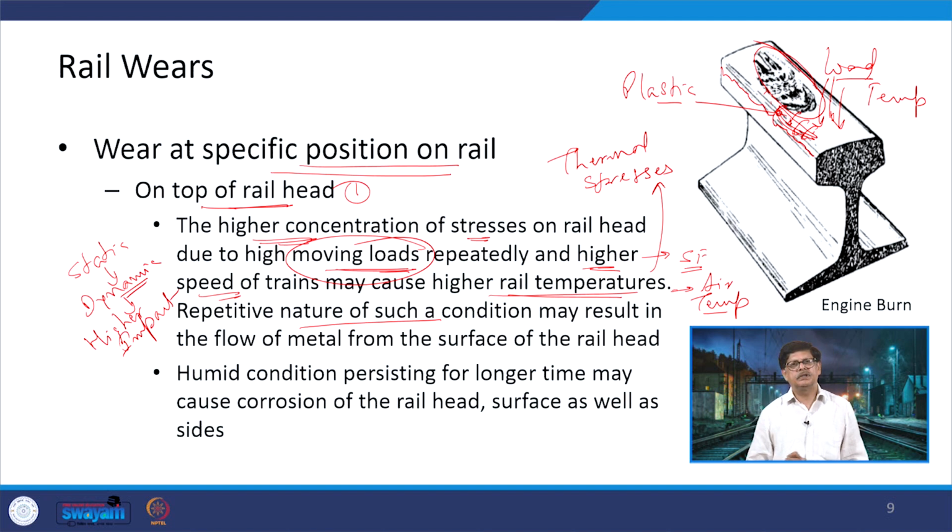Again, if you remember, this is one aspect which we discussed, and if this happens and it comes on the side of the rail head, then it tightens the gauge, because now the space which is left as 1676 mm will reduce in that form. But it shall be within the permissible limits of the clearances with respect to the wheel flange.